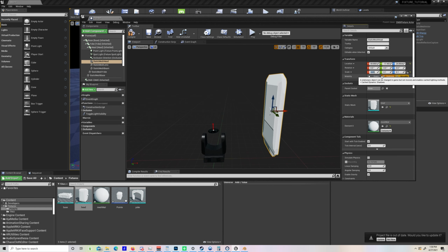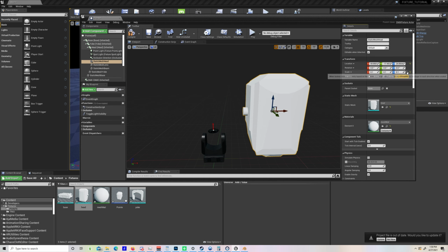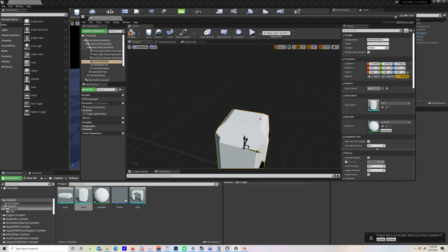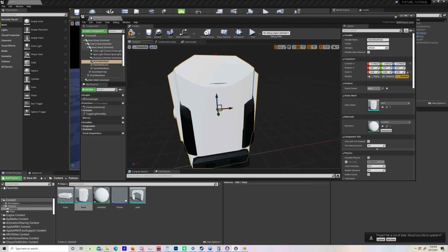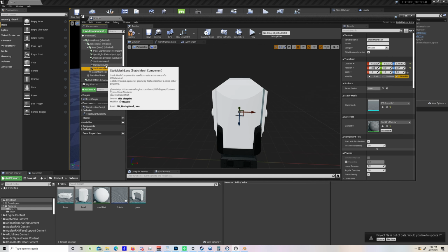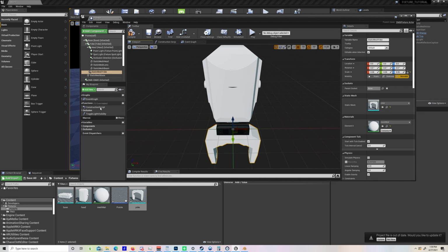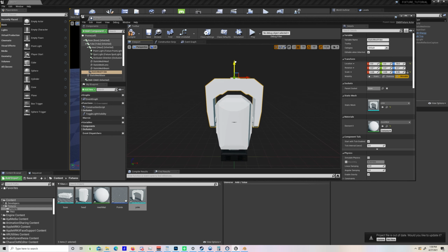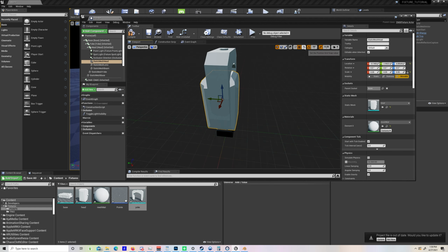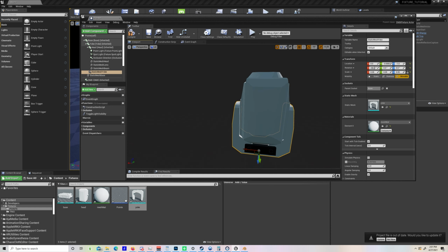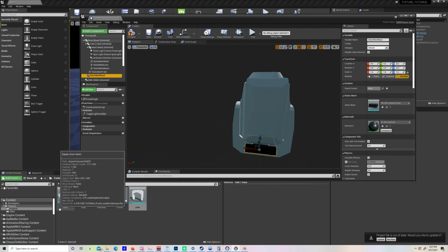I ended up settling at 0.05 as the probable scale. If I were less lazy, I could go back and re-import all the models with this scale, but you can also just resize everything uniformly. It also seems that the model included was oriented facing down rather than up. We move our new model to match our previous positions and orientation using the Transform tool.